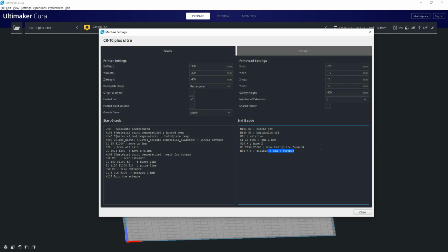Like I said, we have a huge print farm, and I can't be going around to these printers trying to level gantries all day. So we never turn our printers off, which means their Z-axis motors are always locked and always in the proper position. And again, if there's any other info you're looking for regarding Gcode commands, you can look at the RepRap wiki.